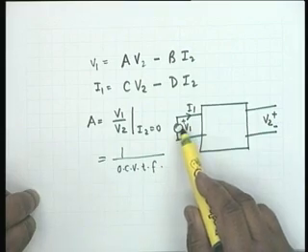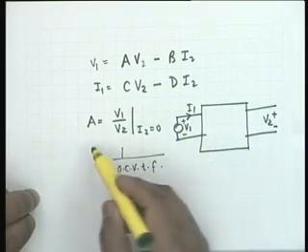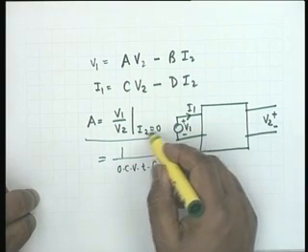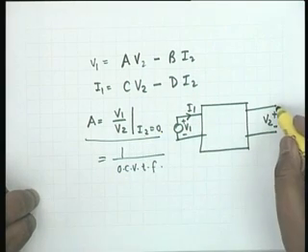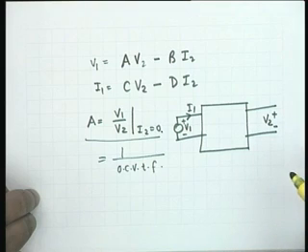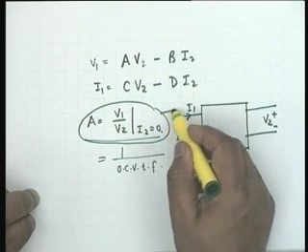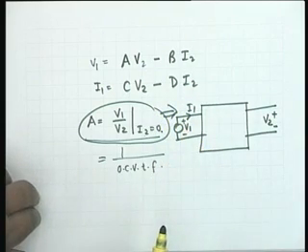So you should have taken V1 as the voltage generator and measured at the other end. That's what I have done. Could I take V2 as the voltage generator? I cannot, because I2 is 0. If I connect a voltage generator here, it will definitely send a current. Isn't that right? And therefore, I am constrained by the definition to use a figure like this.